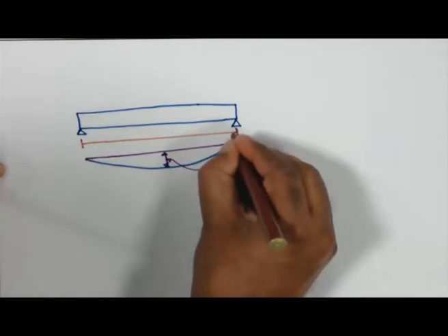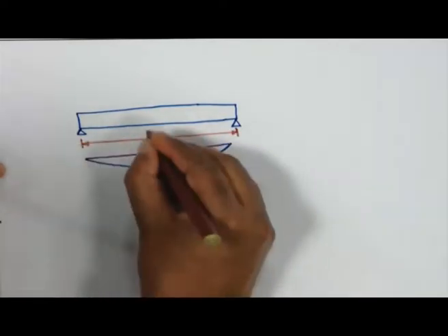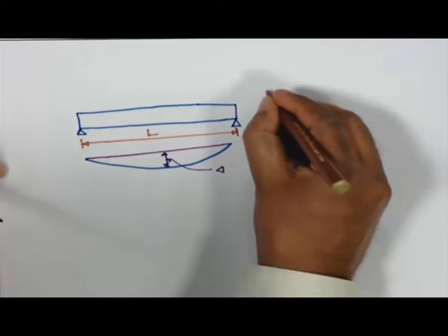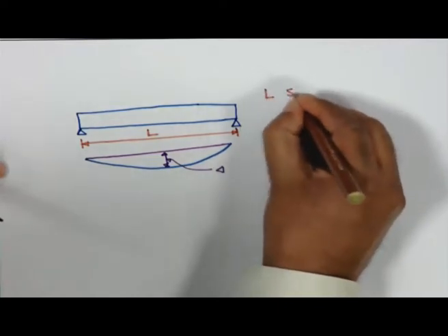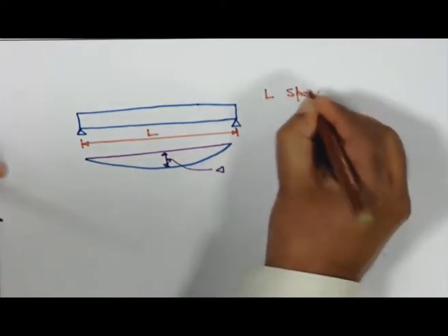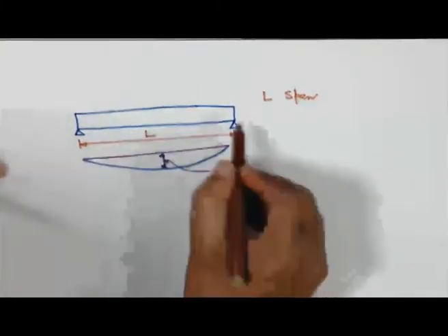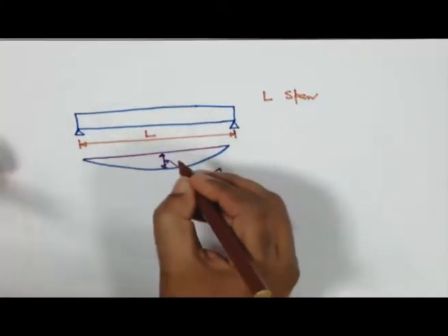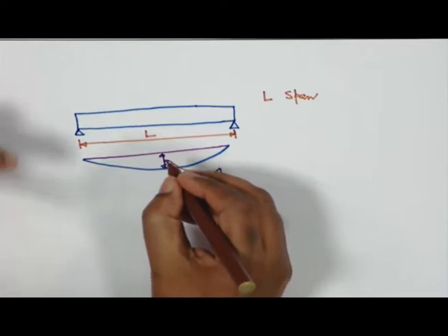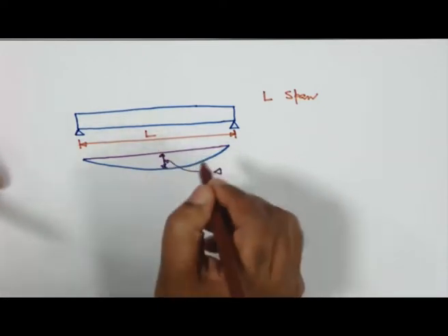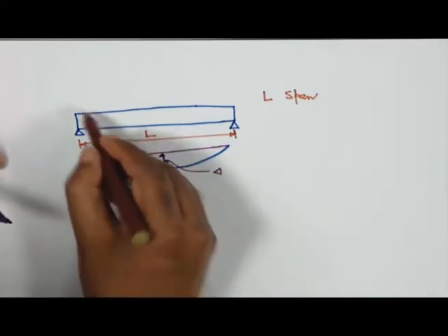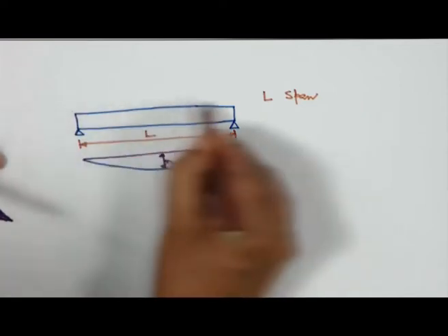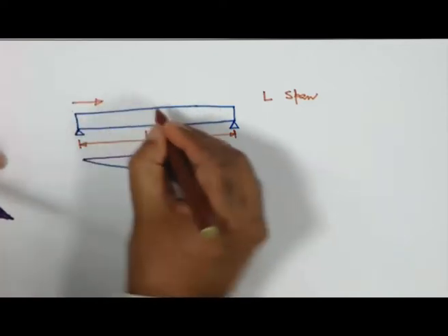But if you consider that book which has become wet or something else, then we will find otherwise. So just to give you an idea of what we mean by plane, even if all the pages slide, the idea is that they remain plane. The maximum strain in the concrete extreme fiber is taken as, please note this vital number, 0.0035.